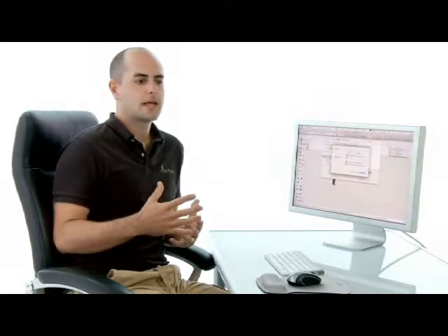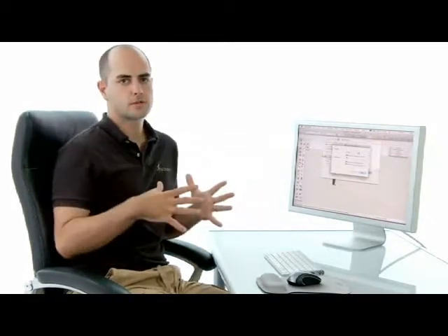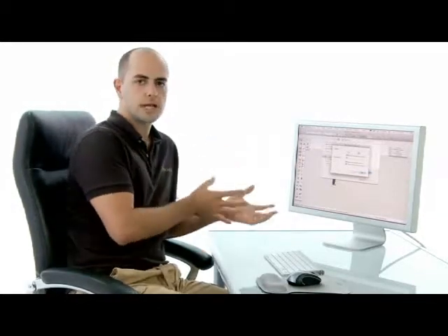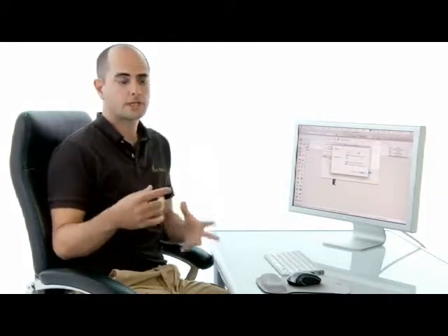Now that being said, if you're working on a project that's a really big project, maybe you've got a survey and you're talking acres and acres of property that's been surveyed. A lot of surveys that I've seen that come into SketchUp from CAD have the origin set way far away from the actual location of the project. They may be using some kind of geo-coordinate reference for the origin of the CAD drawing. If you have the checkbox for Preserve Drawing Origin checked, in that case, you'll find that your drawing could be thousands and thousands of feet away from the drawing origin in SketchUp.